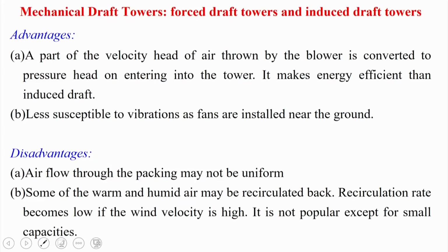Maybe it is apart from the cooling tower, but some disadvantages are also there. Airflow through the packing may not be uniform, because where the fan is placed the air flow rate will be very high, but where the fan is not installed the flow rate of air will be very low. Some of the warm and humid air may be recirculated back due to this type of fan application. Recirculation becomes low if the wind velocity is very high. So it is not popular except for small capacity towers.